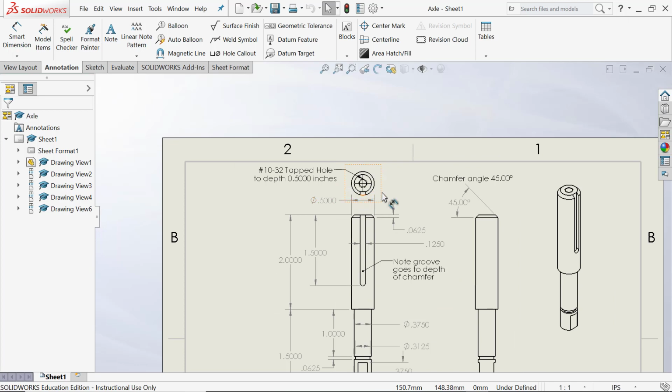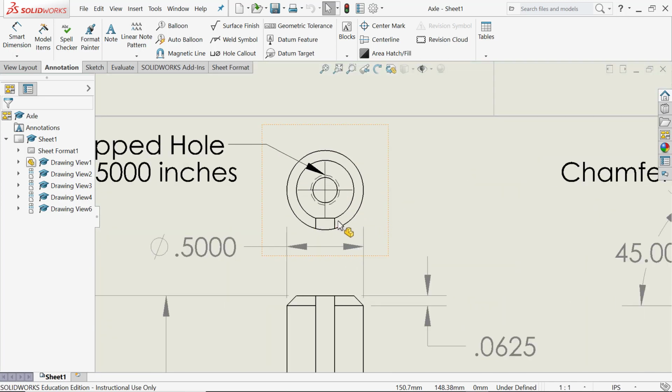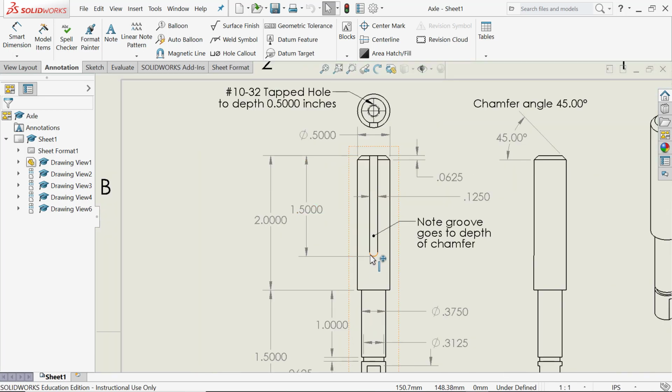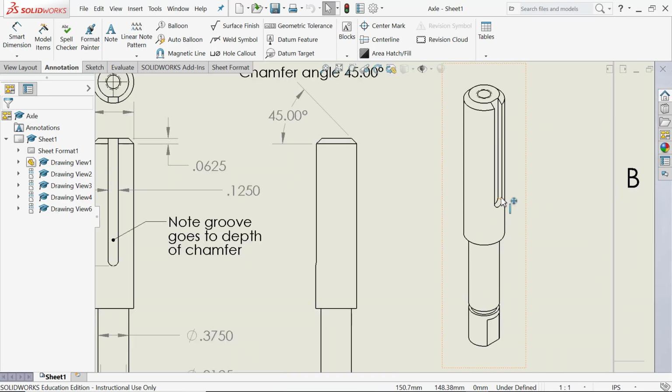So what we'll probably want to do is make that cut by drawing a rectangle on the top of the part with its corners resting on the chamfer, and we do the chamfer before we do the groove. Does that make sense? That way the two sort of link together. And then we'll cut that going straight down from this view, which will produce a groove that comes this way. That groove will terminate with square corners. How are we going to make it end up having these sort of rounded corners? Yeah, we're going to do a fillet there. So after we do the extruded cut, we'll do that.